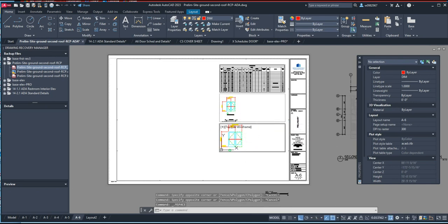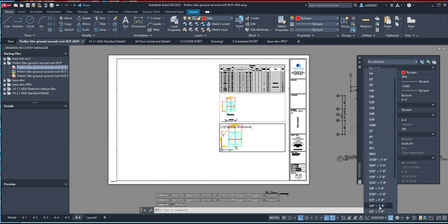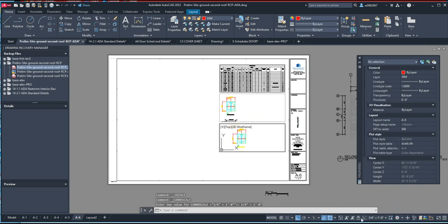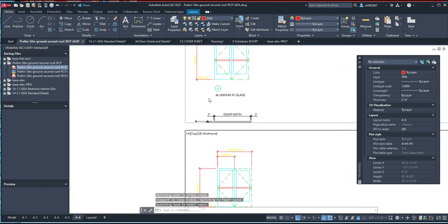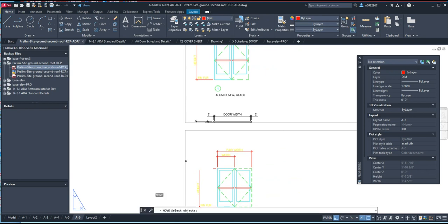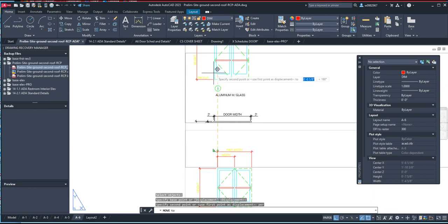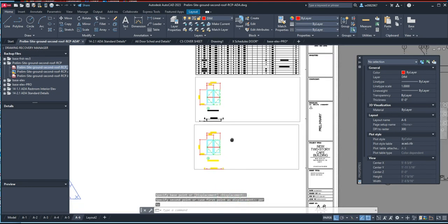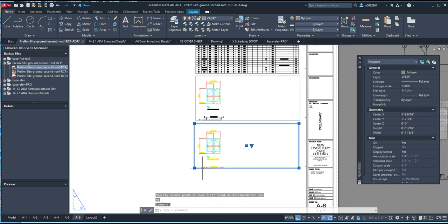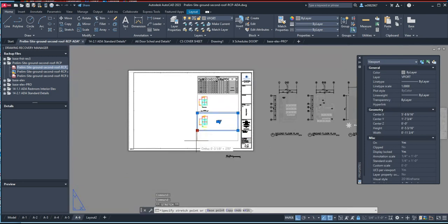And then with this one also, set it to a quarter, and then align that and then lock it. And let's see if they're aligned. Let's just do a move. We're going to move the viewport, select from an endpoint here, and do a perpendicular to this one here. There you go. Now they're aligned. Okay. And this one is actually, I want the bottom one.